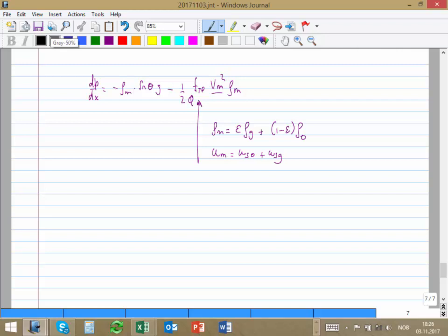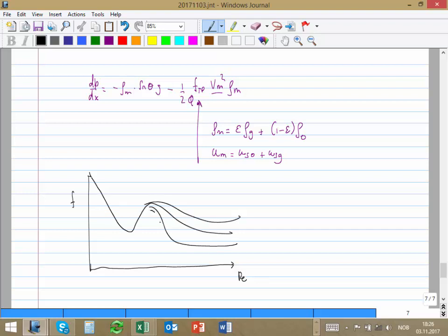The friction factor, if you remember, we had that plot that was depending on... we're going to use just the single phase friction factor. And it did something like this, going up and like that. And for that, I need a Reynolds number. The roughness and the diameter I have, but I need the Reynolds number, that is velocity times density times diameter divided by viscosity.